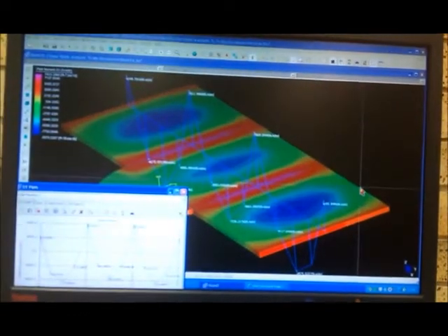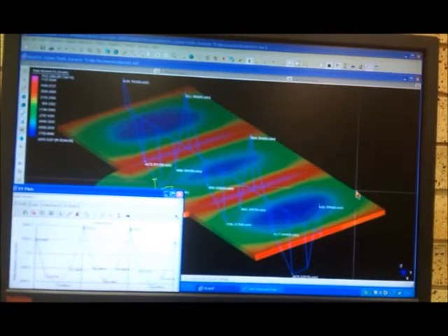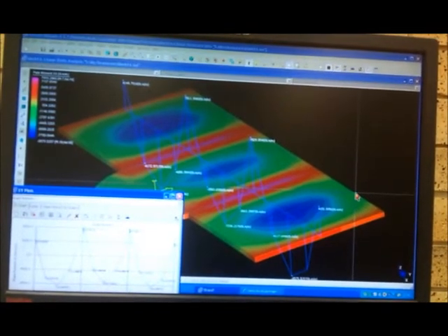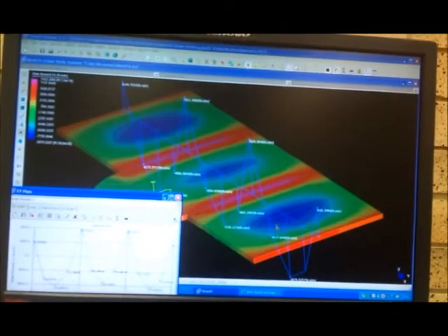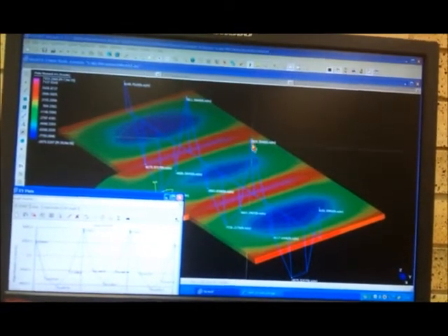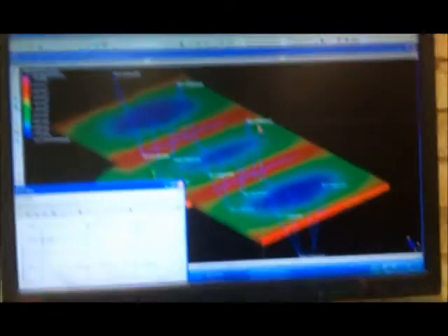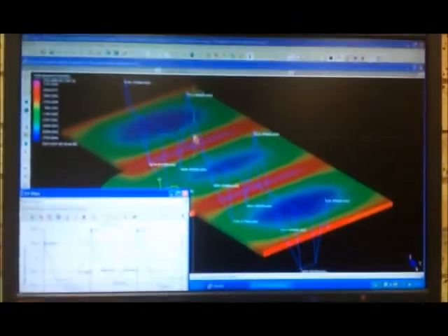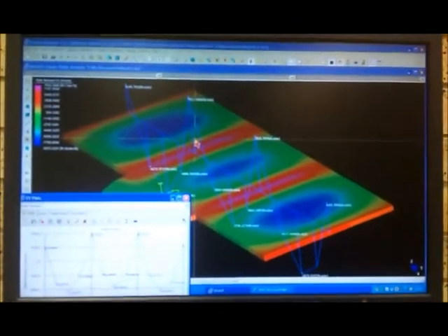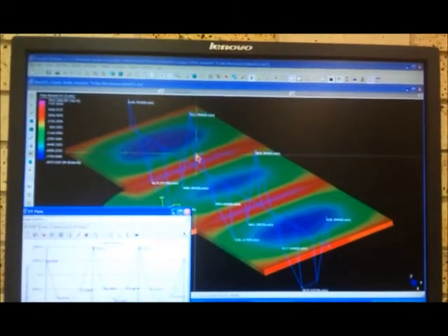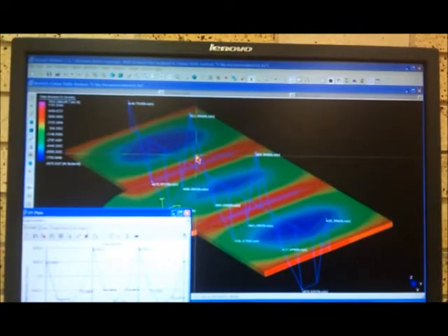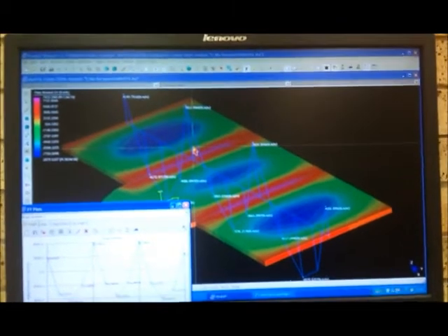Can you see the bending moment values? Yes. So, you don't have to check a color and then go and see what this color is. By putting this graph like this, it will give you straight away the bending moment. This location is this amount and so on. Okay. So now we have checked the normal forces and stress in columns, bending moment in beams, and then bending moment in slabs.